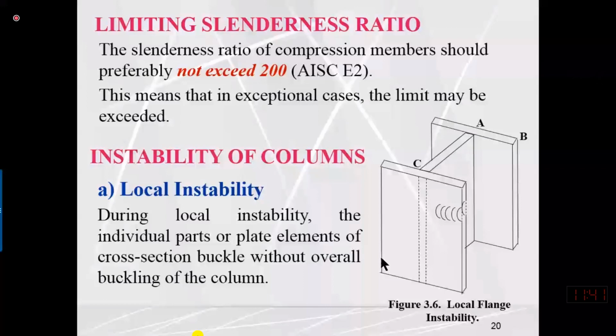Unlike a tension member, a compression member has two types of instability issues. One is called overall and one is called local. Overall stability is referred to as buckling. Overall means the whole length of the member may buckle or bend at a later time. How can we control this? By limiting the slenderness ratio about either axis to less than or equal to 200. This criterion is 300 for a tension member, but for a compression member and a stress reversal member, this value is 200.